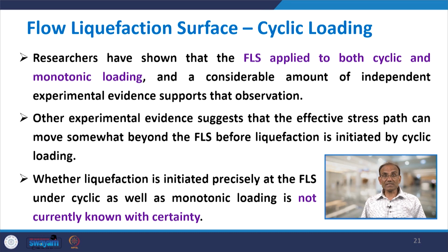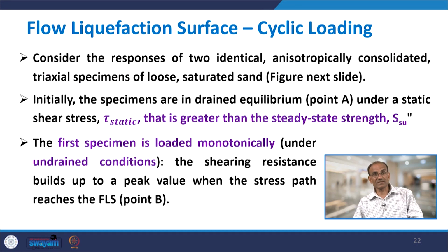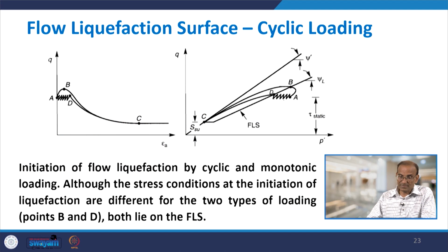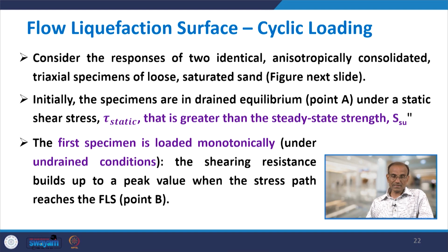Whether liquefaction is initiated precisely at the FLS under cyclic as well as monotonic loading, the issue is this: if you have a combination of monotonic and cyclic loading, which one initiated the liquefaction, whether due to monotonic load or cyclic load, currently cannot be said with certainty. But consider the response of two identical anisotropically consolidated triaxial specimens of loose saturated sand, shown in the next figure. We will discuss these two identical specimens.